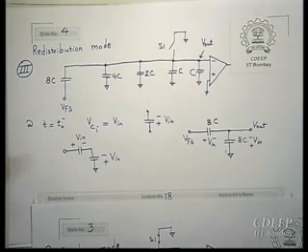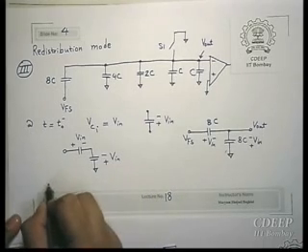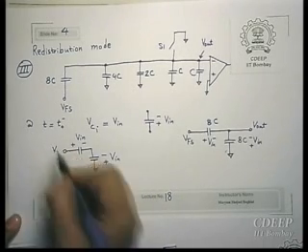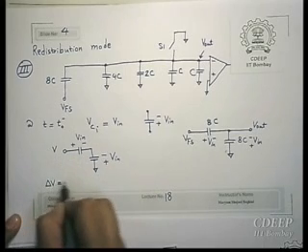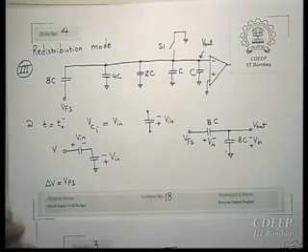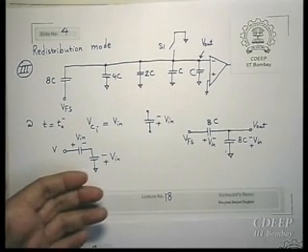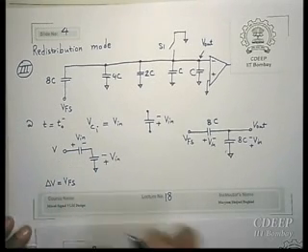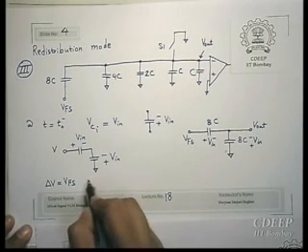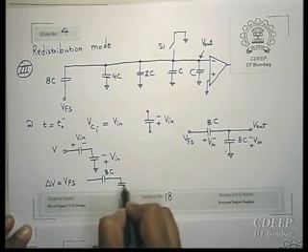It's open, but it is anyway at 0 level. Now you are increasing it to V full scale. So now what will happen? Eventually, if this is V, your delta V is V full scale. Look at this as an operating point. Look at what your delta V is, because this is a linear circuit. Delta V is V full scale. Therefore, you will have a capacitor 8C and a capacitor 8C here.